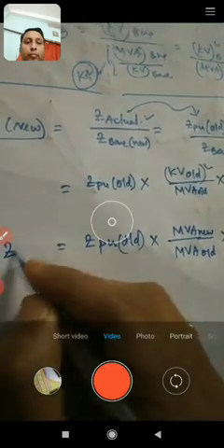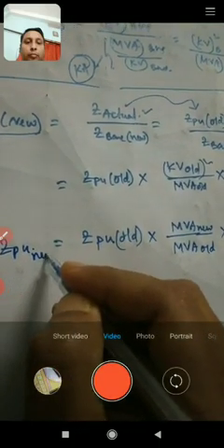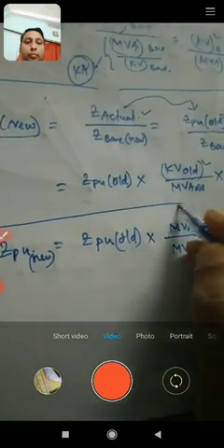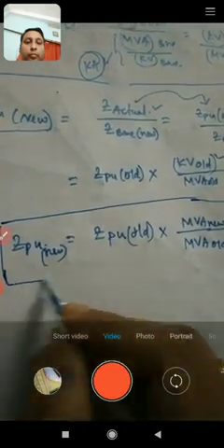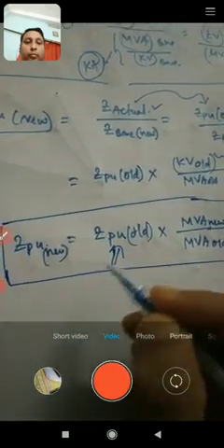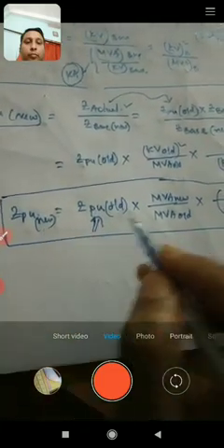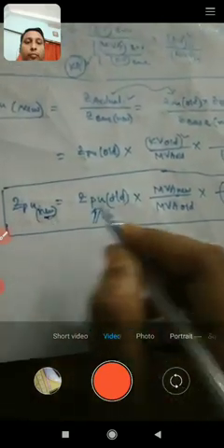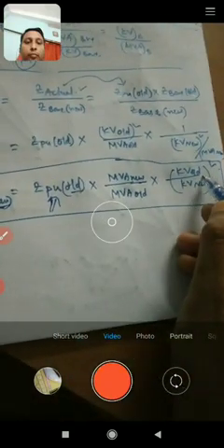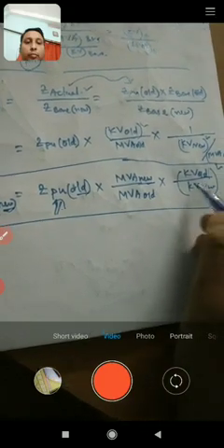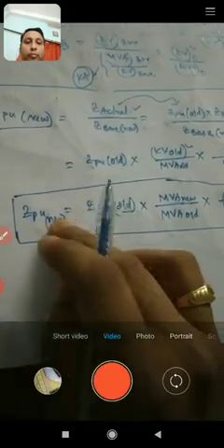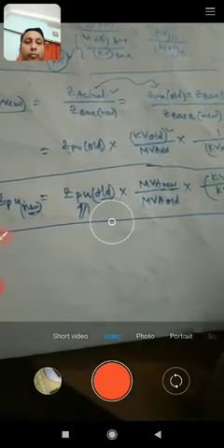So what is this formula? A very important formula: suppose a per unit value is given but on a different base, and you want to change to a new base system. How to remember it? There is a method I used to tell in the class: new, old, you remember it in this way, and the square is in the last, kV square. So new old formula.